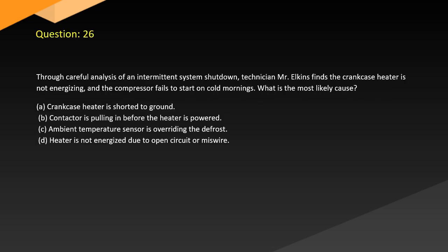Question 26. Through careful analysis of an intermittent system shutdown, technician Mr. Elkins finds the crankcase heater is not energizing and the compressor fails to start on cold mornings. What is the most likely cause? A. Crankcase heater is shorted to ground. B. Contactor is pulling in before the heater is powered. C. Ambient temperature sensor is overriding the defrost. D. Heater is not energized due to open circuit or miswire.